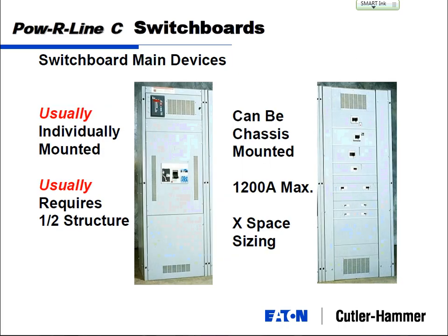So the main devices in the switchboard are usually individually mounted, especially anything over 1200 amps. And they'll just put her in the structure with some devices above it. But we could do it in a chassis up to 1200 amps.